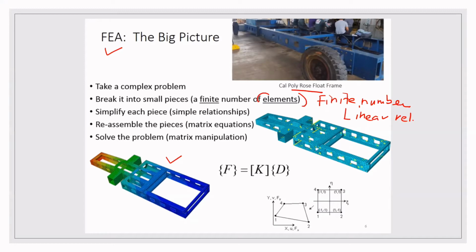between the stress and strain or between the force and displacement. Then we're going to take all of those pieces and show that they have to relate to each other using a compatibility or continuity equation. So we are going to link them together, and this will give us a large system of equations. Then we're going to assemble them into a matrix form and get an equation like what is shown here. Then we are going to solve that matrix equation.